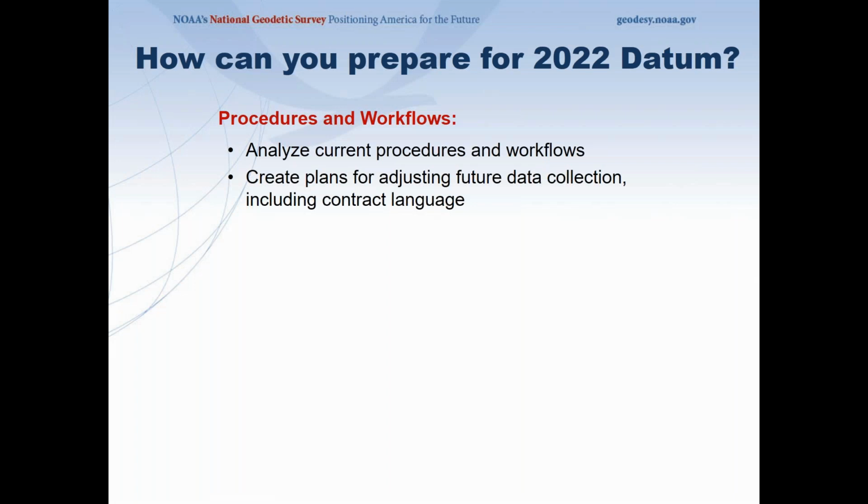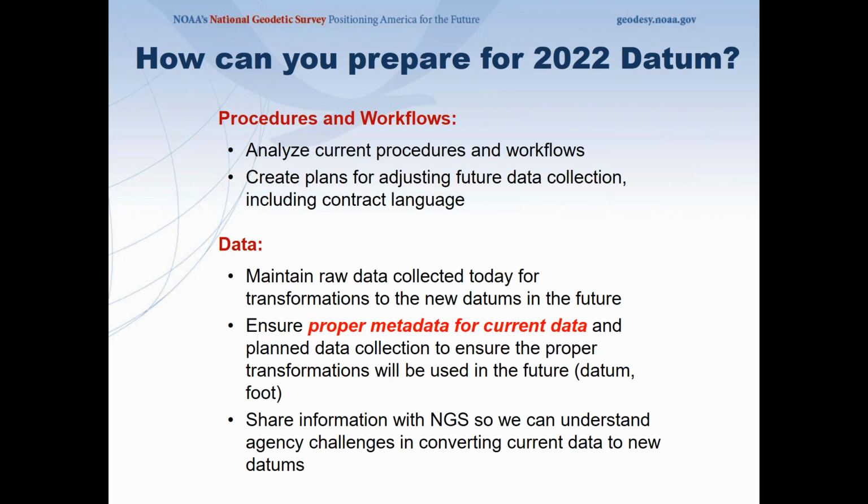So how can I get prepared for the 2022 datum? Well, analyze your current workflow and procedures. See how you're doing things so you can get your flow ready for the new datum. Create plans for adjusting future data collection, including, if you have a contract, into the contract. And maintain the raw data collected today for transformation into the new datum for the future.